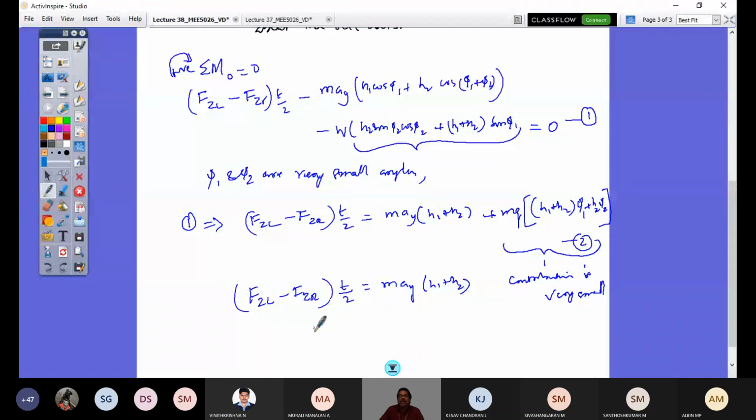What I'm interested in is the lateral acceleration. I can rewrite this as this. During the turn, at the time of tipping is what I am interested in. Tipping about what? The left wheel, right? The left wheel contacts the ground. So at the time of tipping, I know that the right side F_zR is going to be 0.